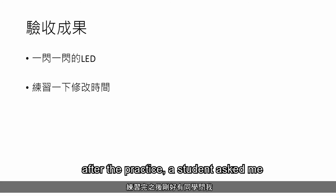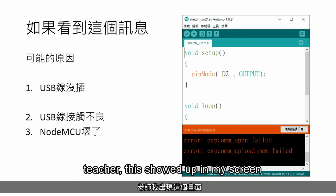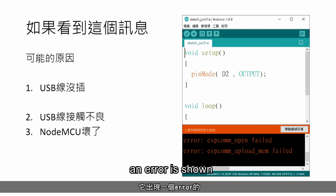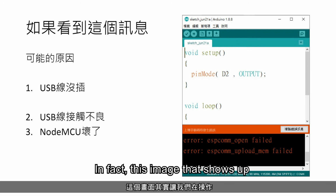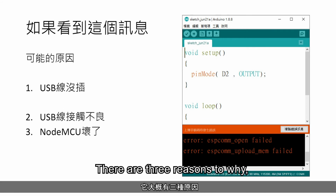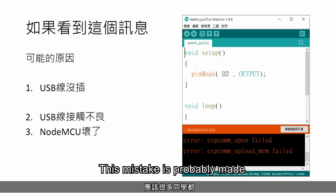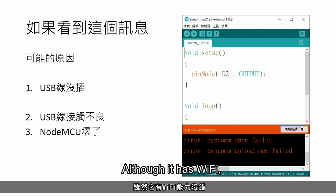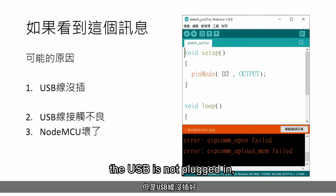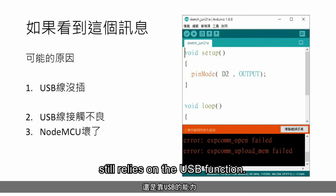After the practice, a student asked me, "Teacher, this showed up in my screen. An error is shown. In my screen, what is wrong?" In fact, this image that shows up during our operation will happen very often. There are 3 reasons why. The first one is that the USB cable is not plugged in. This mistake is probably made very often by students. Although it has Wi-Fi, the USB is not plugged in. The uploading and downloading still relies on the USB function.